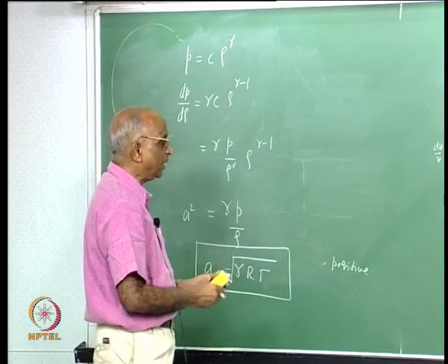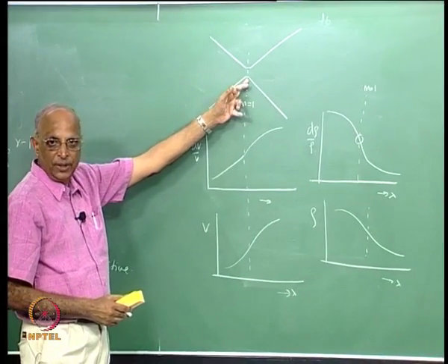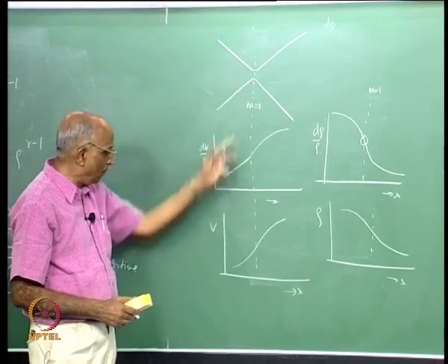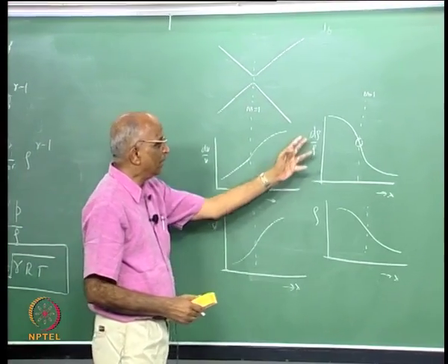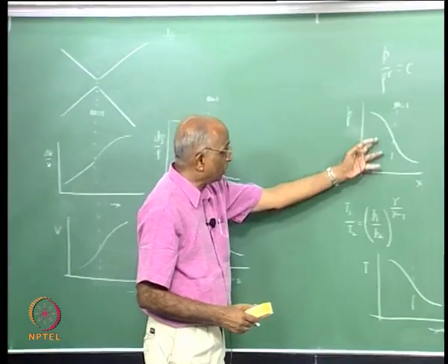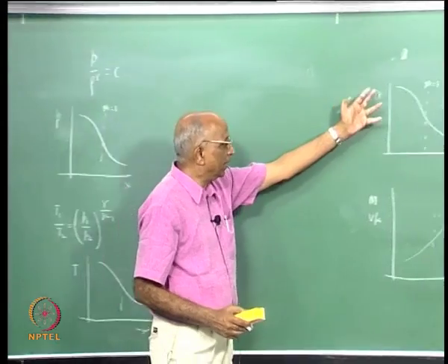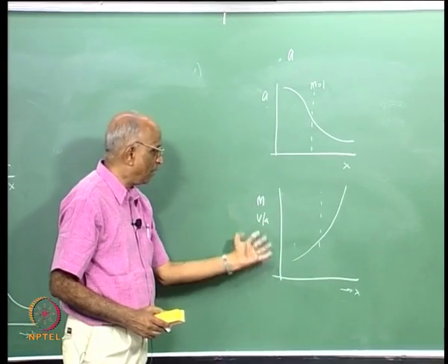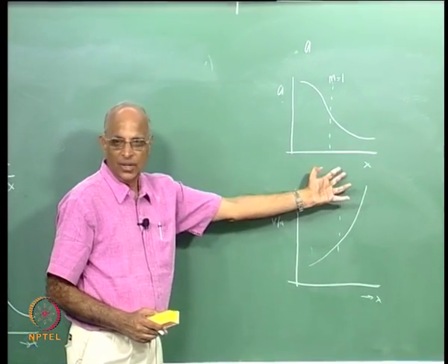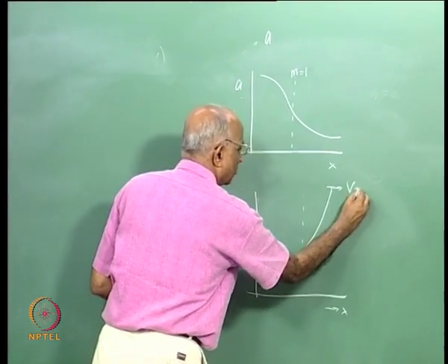Therefore let me repeat it again. dV by V progressively increases when I have Mach number 1 at the throat, velocity increases, the density decreases rapidly at the throat, pressure also decreases, temperature decreases, the sound speed decreases along the length, and therefore the Mach number increases along this. And we are interested in a high value of Mach number or jet velocity at the exit.